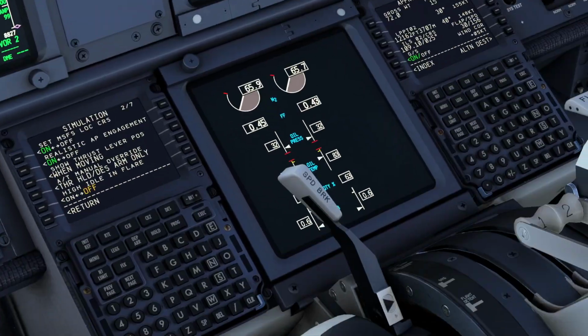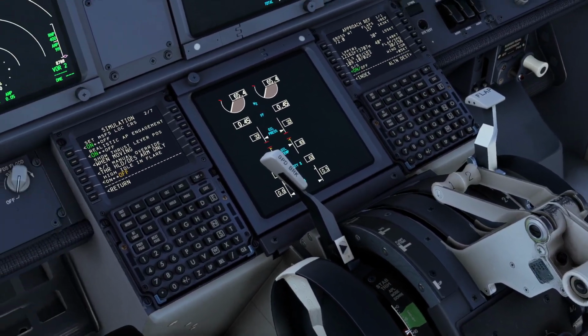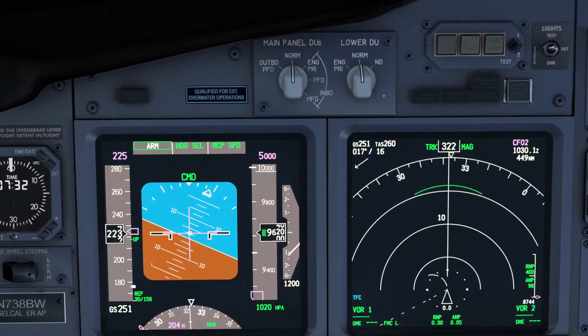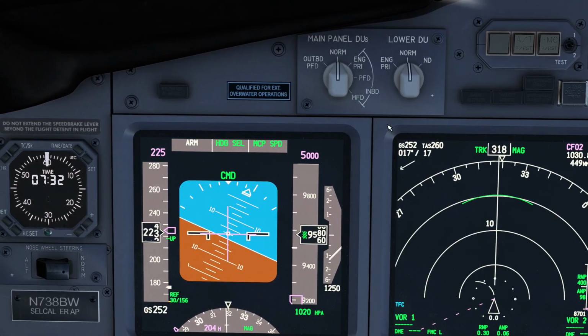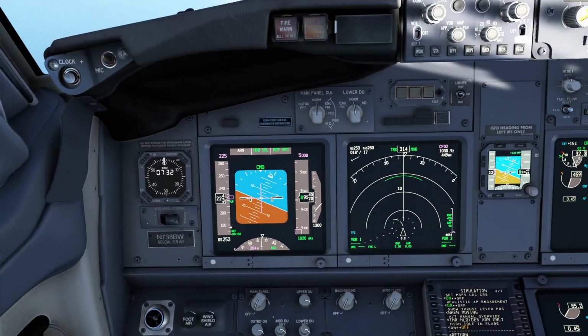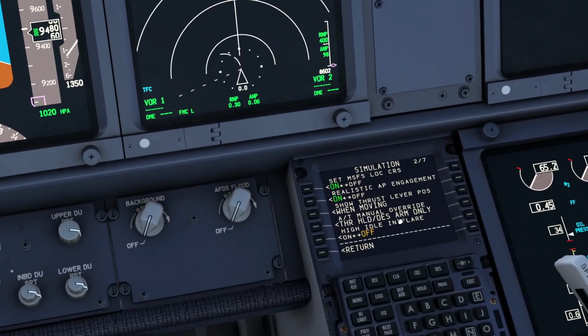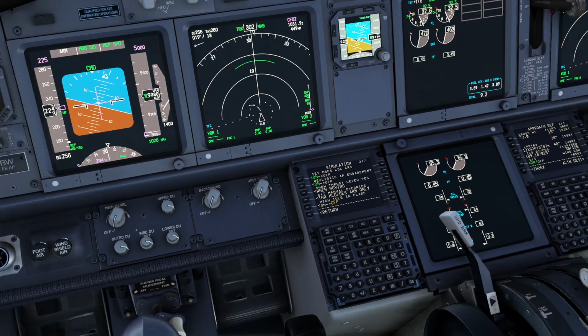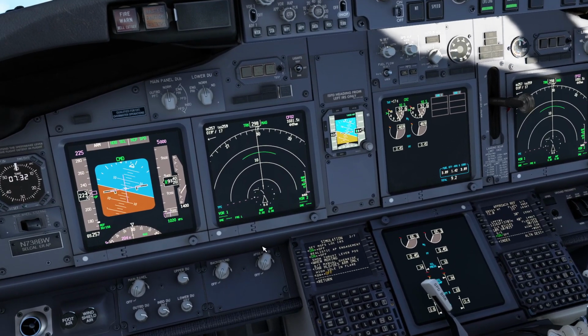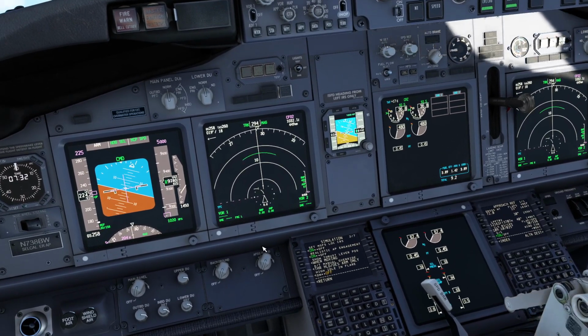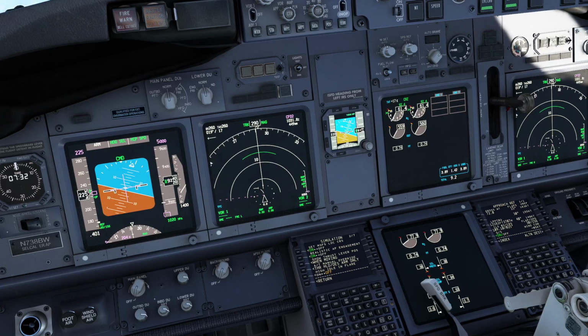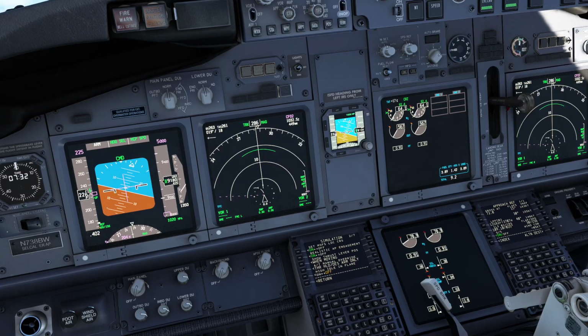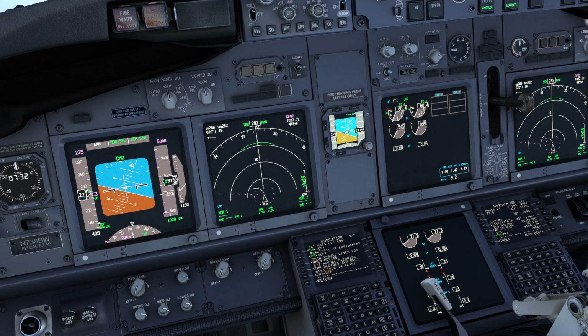That means now the thrust lever is at idle and the auto throttle is not going to change my thrust lever position until I select a different mode. In this case, when we have then descent arm, this is the case, or during the takeoff throttle hold, now anytime I move my thrust lever, it accepts. So I have manual control of my thrust levers right now. Okay. So this is up to you.